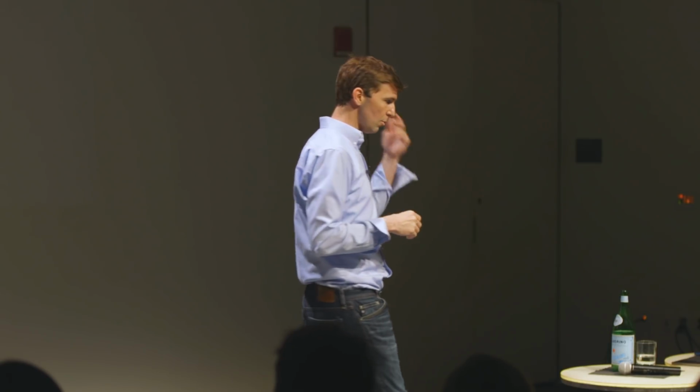And within this, we can also make these parallel devices. We can make mechanisms by folding. That's a very simple concept, but the implementation of it is basically if I have rigid materials surrounding a compliant material, that compliant material then describes a fold, describes a weakened region that we can then array however we want throughout this device and then create these linkage mechanisms which can create arbitrary degrees of freedom. So I can get anything. Think back to the most complex pop-up book mechanism that you've ever seen. We can do that, but we can do that now at arbitrary scales, to very small, even smaller than what I'm showing you, to arbitrarily large if you'd want, although there's better ways to do things at larger scales.